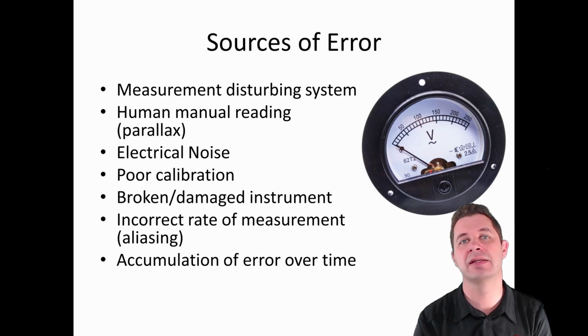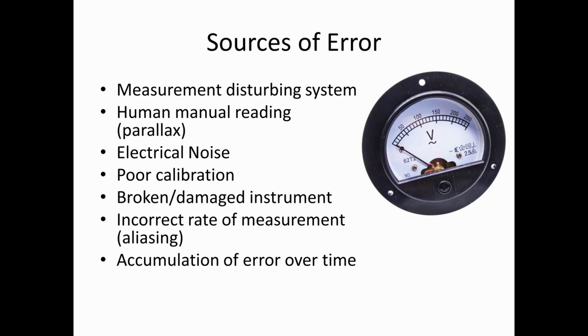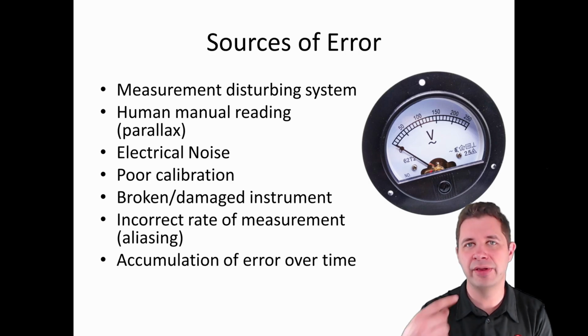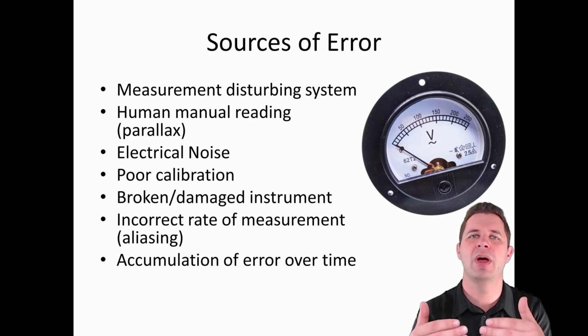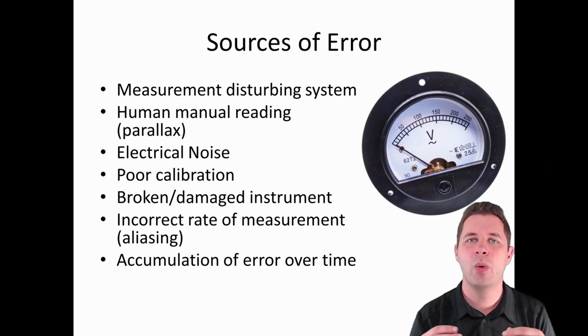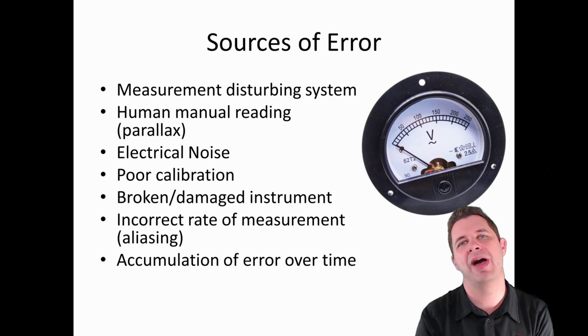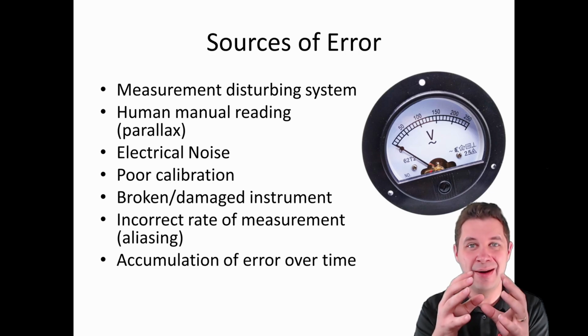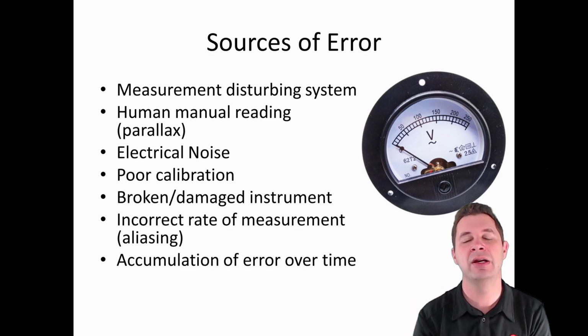And we might have some sensors where error accumulates over time. For example, if we're developing an inertial measurement unit that we use sometimes for navigation, with gyroscopes and accelerometers and things, we can have an error that accumulates over time as we integrate that data. We measure how much we've accelerated or decelerated, and we just keep on measuring those values and adding them together, and each of those will have an associated error with it. When we add all those together, our possible error size, or area of uncertainty, keeps on increasing and increasing.